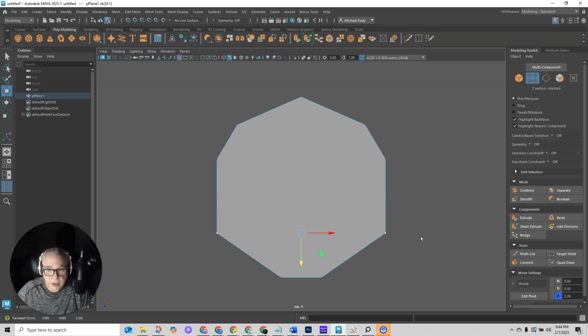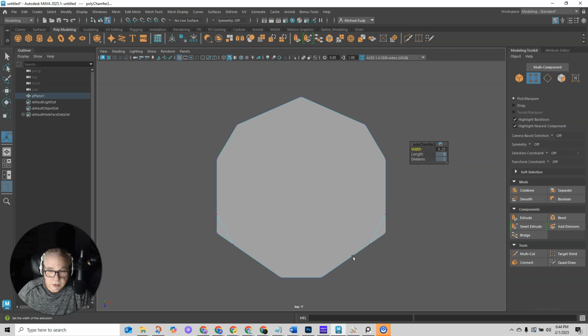So I'm going to go ahead and pick these 2 points, and I'm going to do a bevel. And then what I'm trying to do is I want this length and that length to be the same. You'll see these are bigger than this now. Let's try maybe a 3.5. Okay, so now this and this are very close to being the same length. They don't have to be perfectly the same length, but that's kind of what we're shooting for. So that 3.5 seems to work.